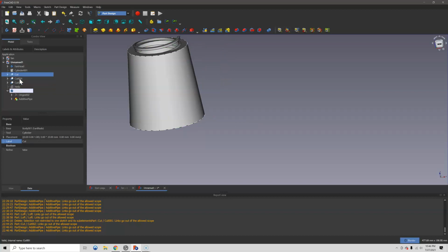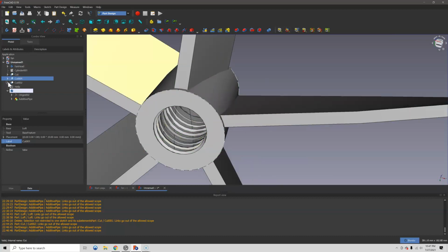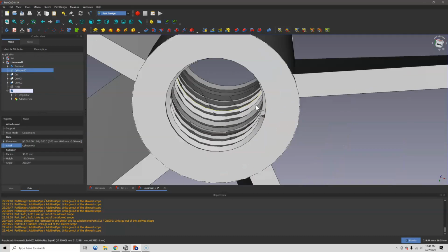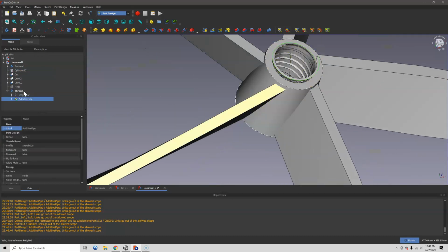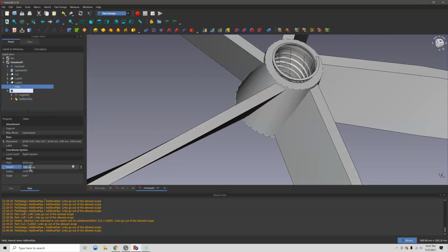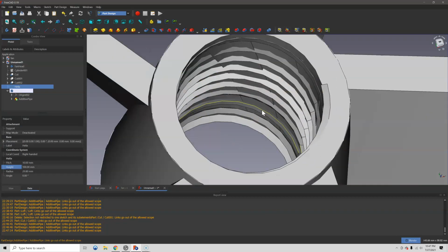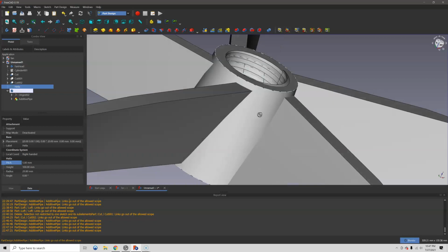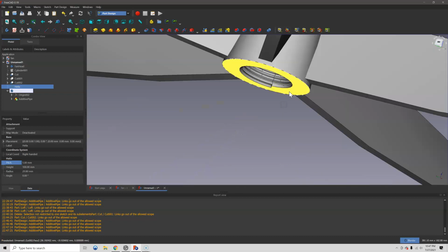It's going to show everything. I'm not sure what this is, but we don't really need to worry about that, I guess. But basically, that is the fan. It's a little high, so we can make it shorter. And you know what? The thread is actually spaced apart, so why don't we set it at 5, so now we get a lot more threads, because of a lower pitch.